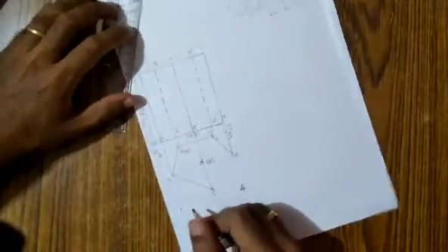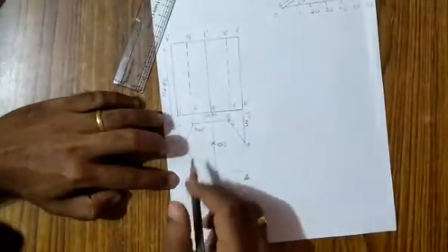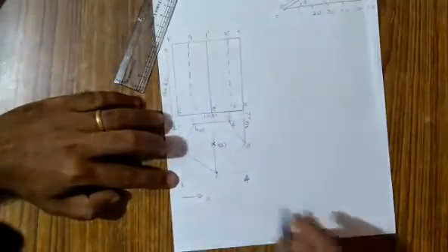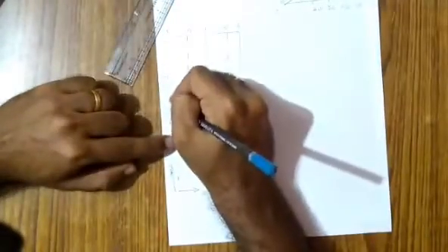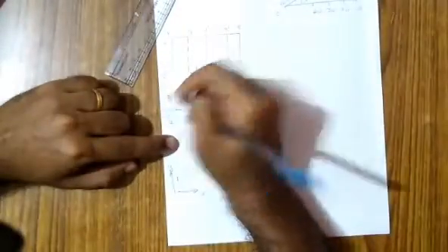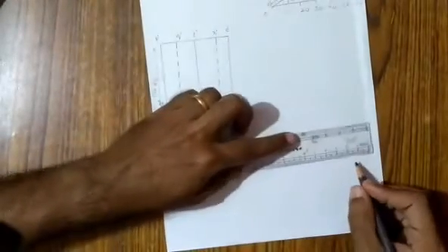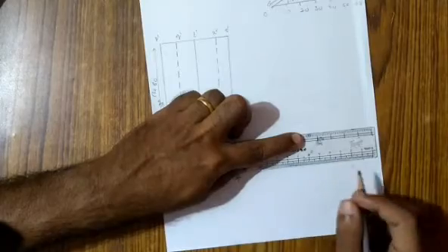So this is the front view of the solid. So in the top view, this plane will be your XY plane. So this direction is your X direction, this will be your Y direction, and all the height from the ground will be your Z direction. So for drawing the isometric view, first let's start by drawing the base.